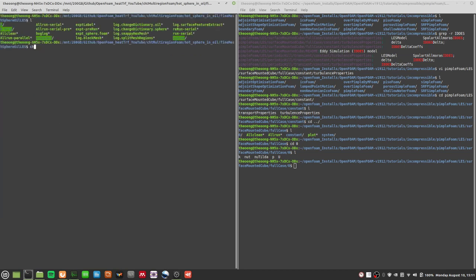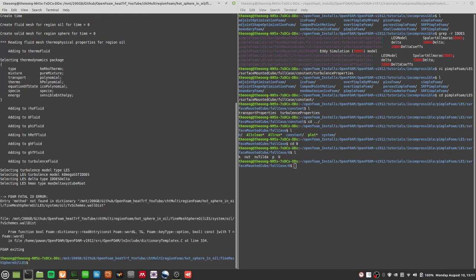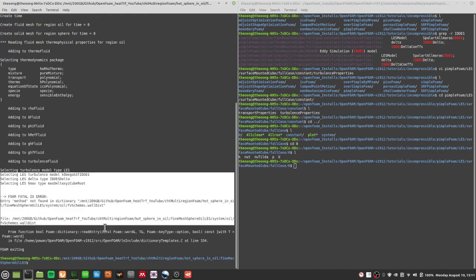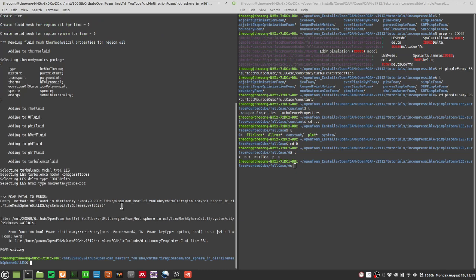Alright, so let's run chtMultiRegionFoam, and again there will be some errors here because you will need a few things. You need not just the fields here, you will need to add entries into your fvSchemes and fvSolution. So let's go through it one at a time first.